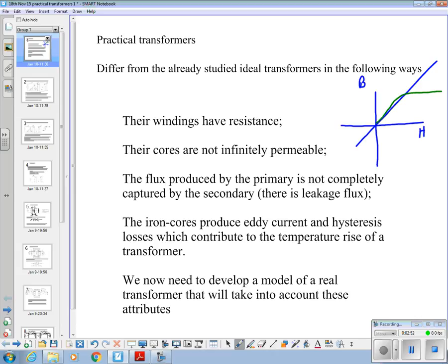And you might have seen this defined where we talk about another one of these losses, the hysteresis losses, when it comes back down again, because remember with the transformer it's AC and we are magnetizing it in one direction, then back and then in the other. That area in there represents a loss, because when we turn it all the way off again, there's some magnetism left that we need some reverse current to get rid of before we start creating a field in the opposite direction. So you get what's called hysteresis losses in a transformer.